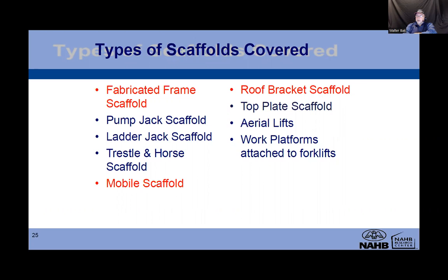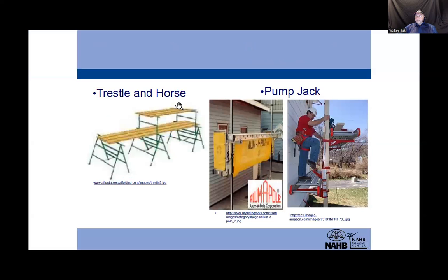Sometimes some companies in 1 day will do two: fall arrest, working on heights, and the lift ticket. The working on heights is basically if you need to step on a ladder or scaffold, and the lift ticket is if you use any of the mechanical devices such as a scissor lift or a boom lift. If you don't have those, do not get yourself on any kind of height using anything on a construction site.